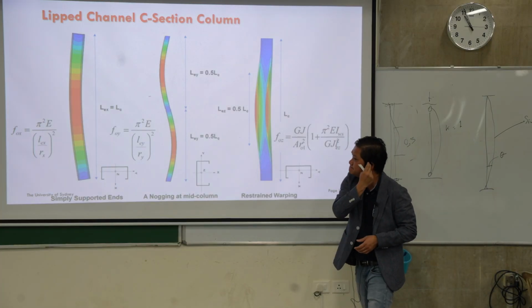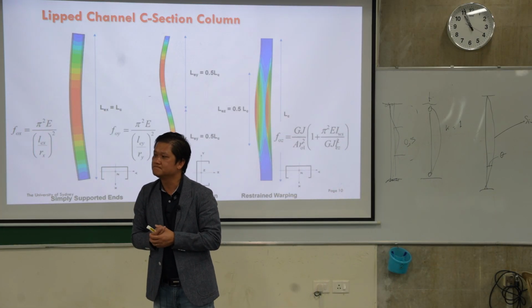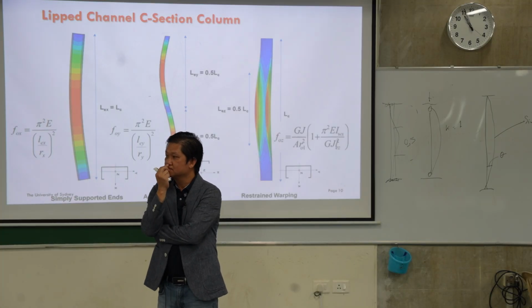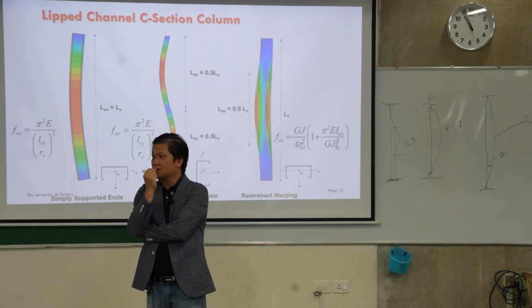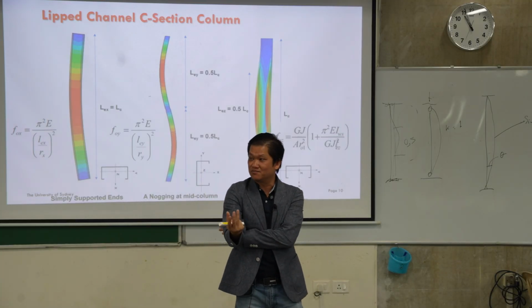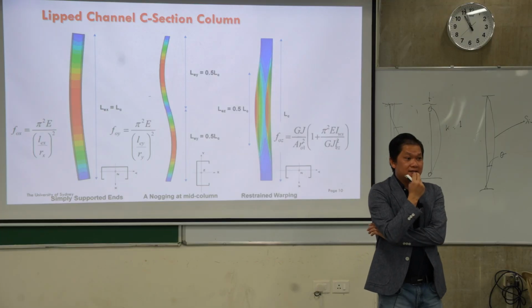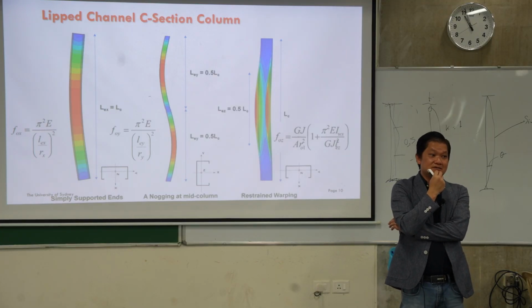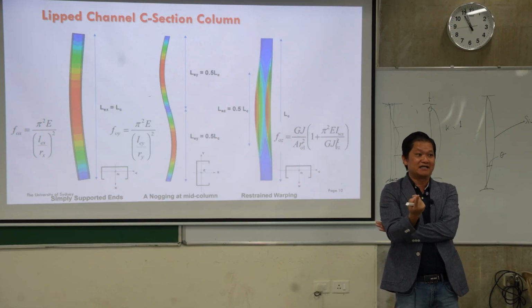So yes. I don't know if I can be mistaken, but I think what he's asking is that there are two types of restraint. One is a restraint for twisting, one is a restraint for warping. The twisting restraint is only to prevent the twisting in this direction. Warping is the movement along the length. So warping restraint is the boundary condition of torsion. If it's simply supported, the rotation is arrested, warping is free. That's right. So if it's simply supported, warping is free.